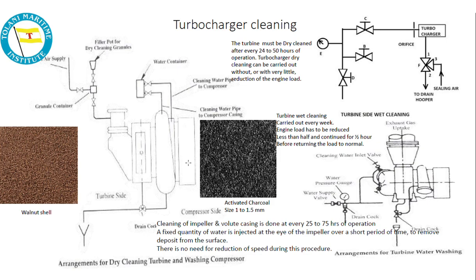Now, when we are talking about the turbine side, we have two things, water washing as well as dry washing. But it is advisable that the turbine be dry cleaned after every 20 to 50 hours of operation. Turbocharger dry cleaning can be done with little or no reduction of engine load. At full load we are doing this turbocharger dry cleaning.